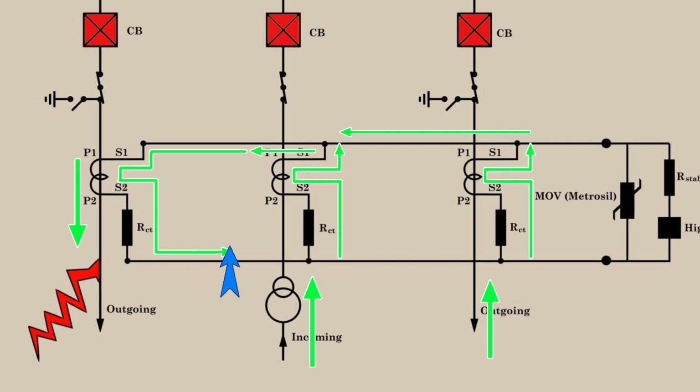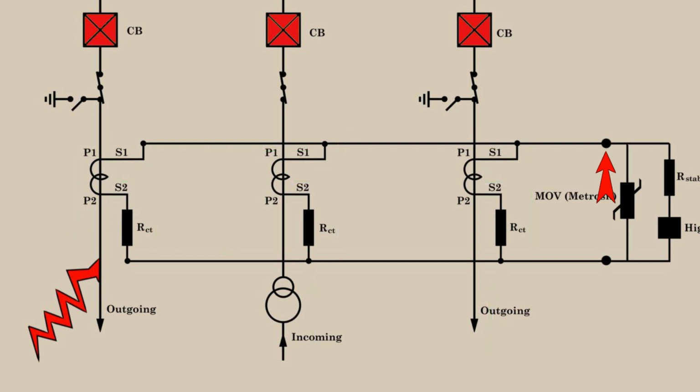So as per Kirchhoff's current law, the summation of these three currents will be 0. That means here I1 plus I2 plus I3 equals 0. So no resultant current comes to this one, meaning the terminal of the relaying arrangement. So there will be no current flowing through the relay, so the relay will not act.